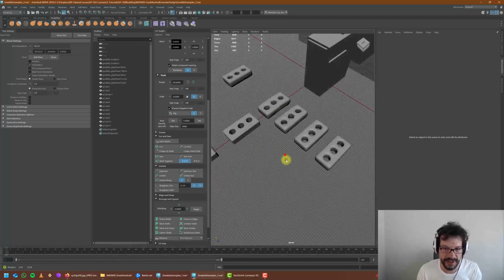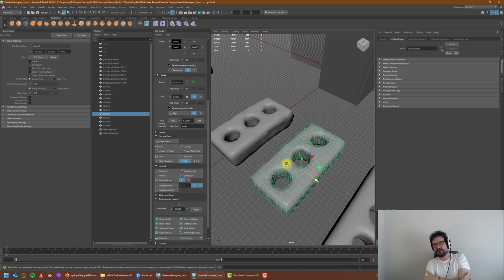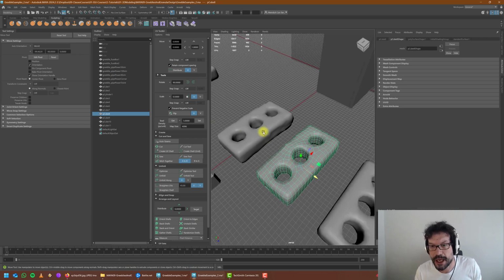you can do the other bricks as well. And you don't even have to go create a higher poly version of it. Well, if you want to, you can still do that. Obviously, you make a copy of this, smooth it a bunch of times, like 3 or 4 iterations even, go with the sculpting tool, add a bunch of details using stamp or whatever, and then match them together in Substance Painter and create variations again, obviously.